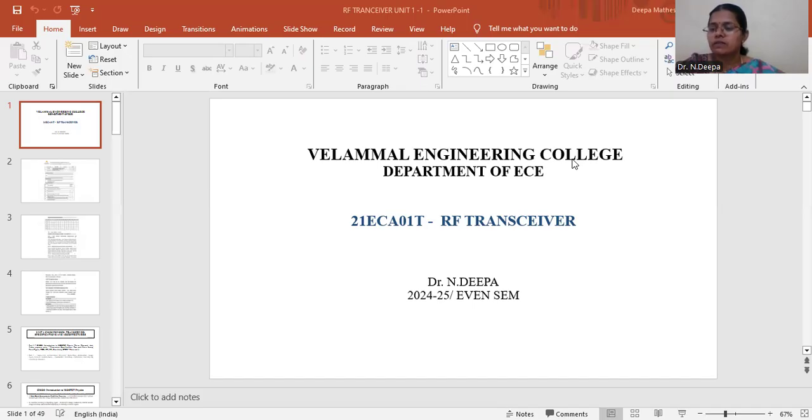The primary difference between RF design and low frequency analog design is the type of analysis performed on the circuit. In RF design, the steady-state operation is of primary concern. The behavior of the circuit is often modeled in frequency domain with attention focused on signal fidelity, noise, distortion, and interference. When modeling a modulated signal on RF carrier, a hybrid time-frequency domain analysis is more efficient, where time domain focuses on the dynamic signal changes and frequency domain focuses on the RF carrier and its harmonics.